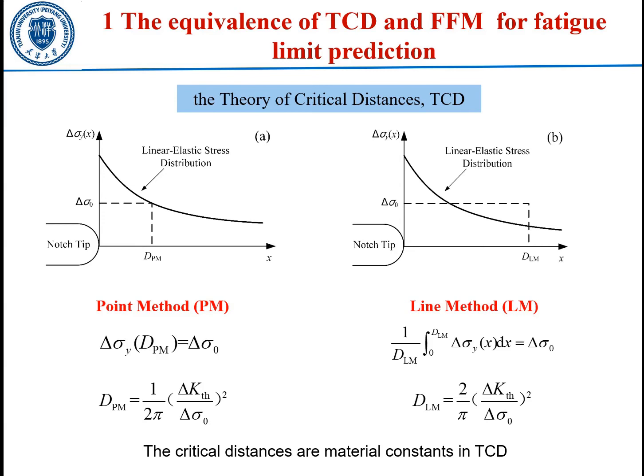Now, let's start with the first content. I believe most people attending the meeting are familiar with the TCD. In our work, we only considered the point method and the line method. We should point out that the critical distances are material constants in TCD, depending on the fatigue limit and the fatigue crack growth threshold of the considered material.